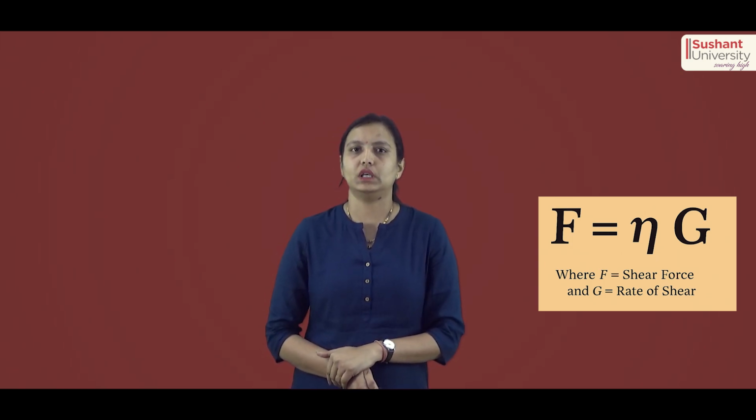So what is rheology and what is viscosity? Rheology is the study of flow properties of the liquids, whereas viscosity is the property of any liquid to flow. Okay. Then what is the formula of viscosity? F/A = η G, where F is the shear force we are applying on any liquid to move it and G is the rate of shear.